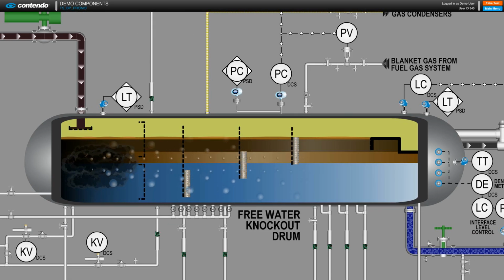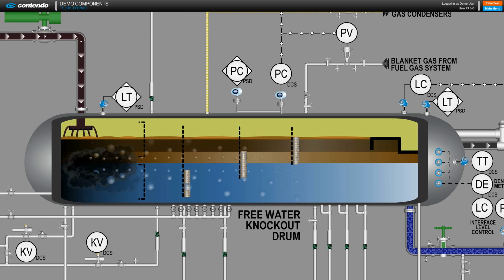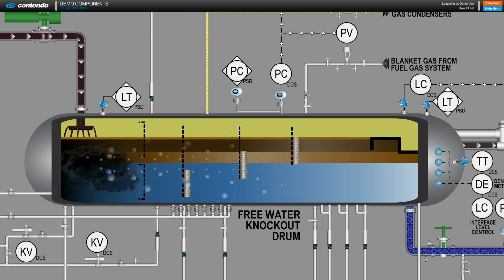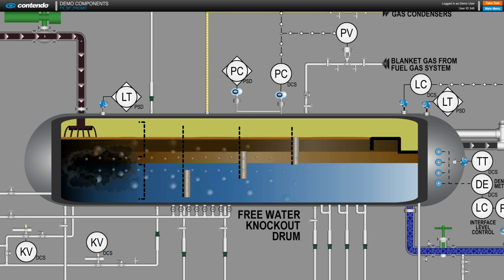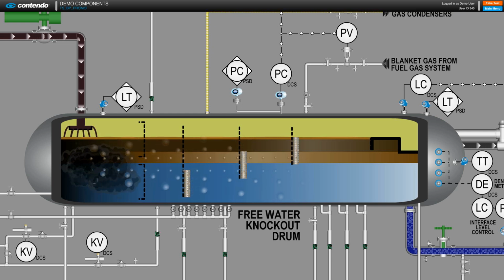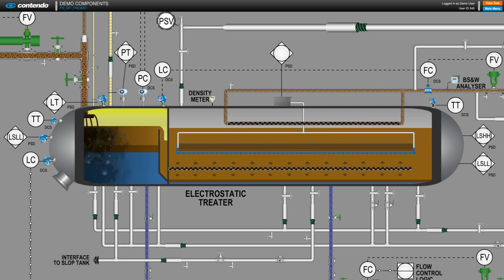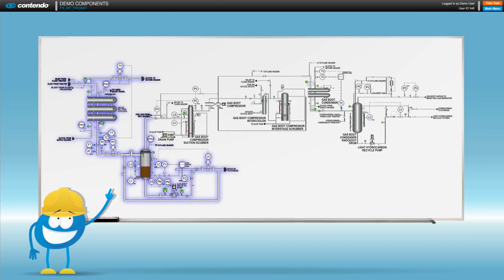We follow the produced emulsion through the bitumen inlet section of a SAGD central processing facility where bulk separation of oil and water occurs in a free water knockout. The resulting produced emulsion diluent mixture then has most of the remaining water removed in an electrostatic treater to produce dehydrated dilbit. The dilbit flows through the sales oil stabilization system gas boot where it is reduced in pressure to bring it to sales specification.